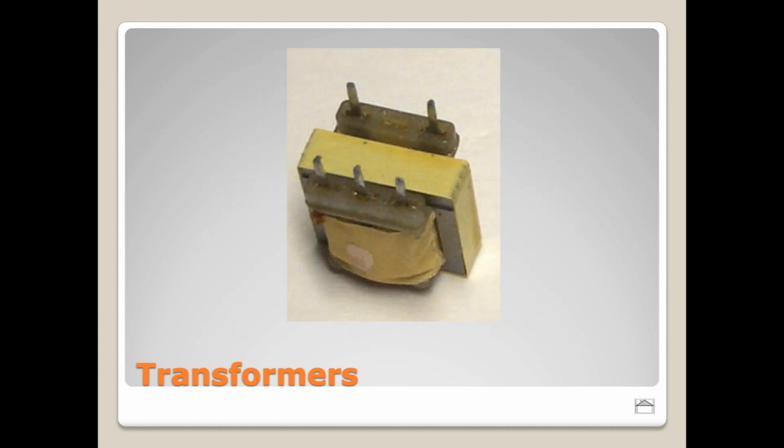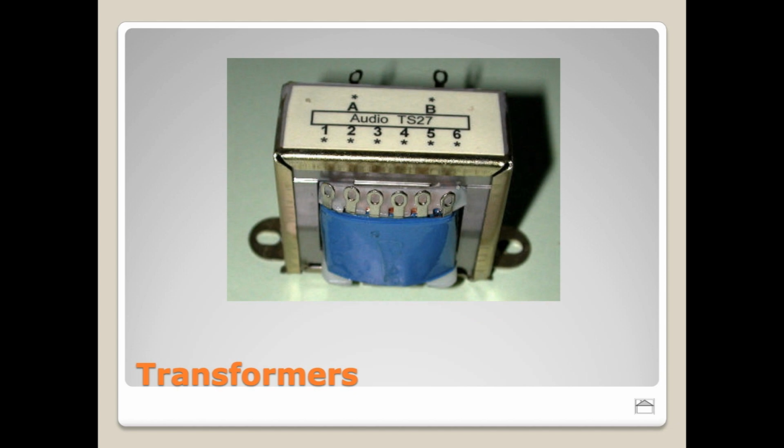So you can see in both of these cases, we don't have simply 2 terminals on both sides, right? We've got some additional terminals that are present here. To really know what these terminals do, you have to really look at some documentation. You can certainly run some voltages through this stuff and figure out what's coming out on the other end, but without really knowing how those coils are configured and wired together, things can get really confusing really fast.